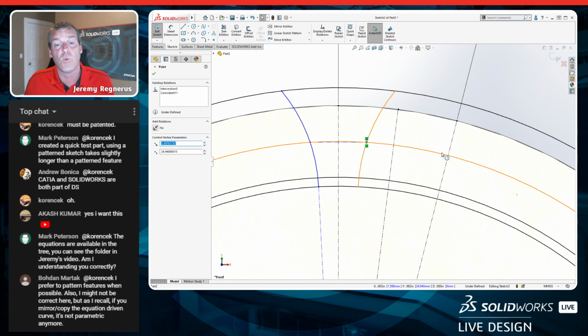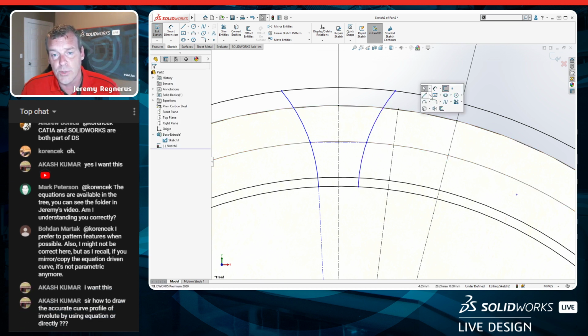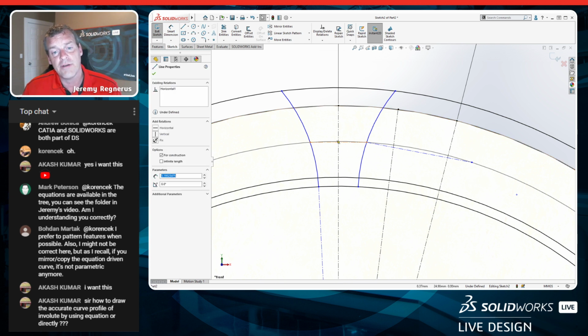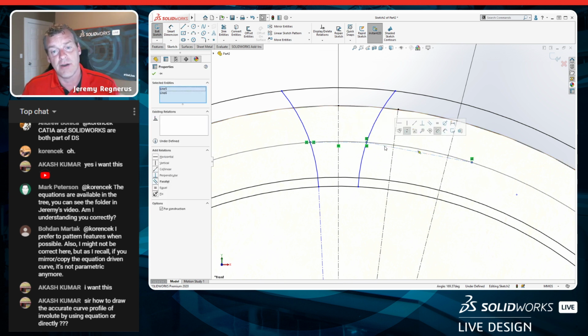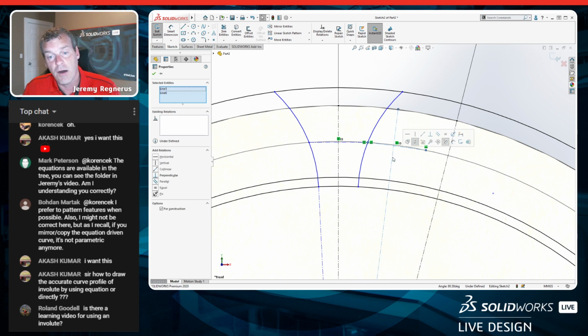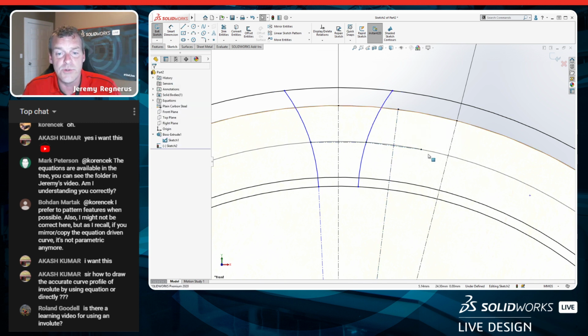I'm going to show you a really simple way to use sketch geometry to solve a lot of this for you. On the tooth next to it, we're going to create another center line. And I'm going to just draw this out and make sure it touches this pitch circle. I know that the width of the cutout needs to be the same as the width of the tooth on that pitch circle. So I'm going to go ahead and say those are equal. Now, that's still not giving me a lot of definition right there. The thing you'll notice is this line is perpendicular to this line. Well, guess what? This line and this line also need to be perpendicular. And when I do that, that defines that width for me right here.